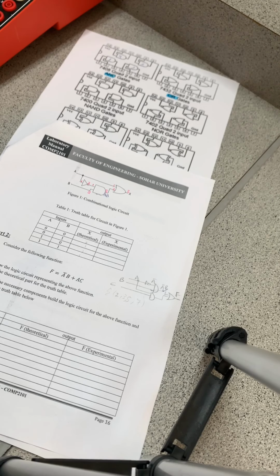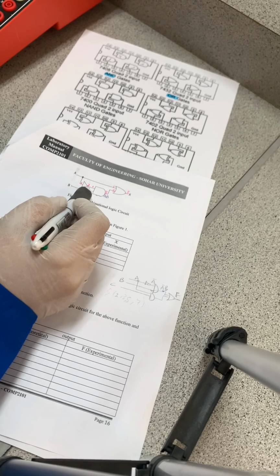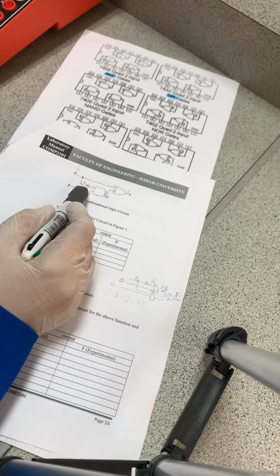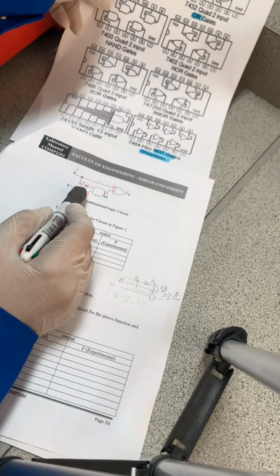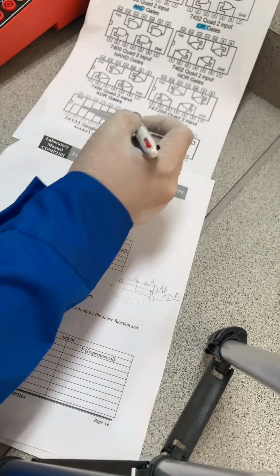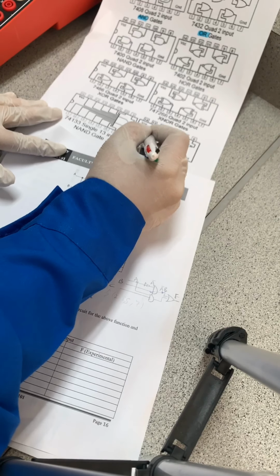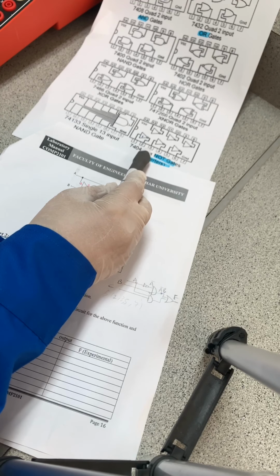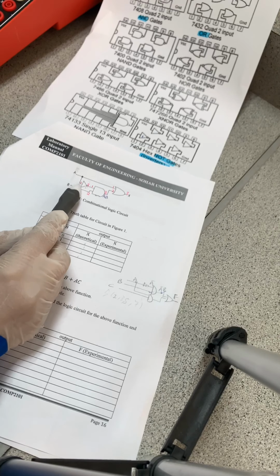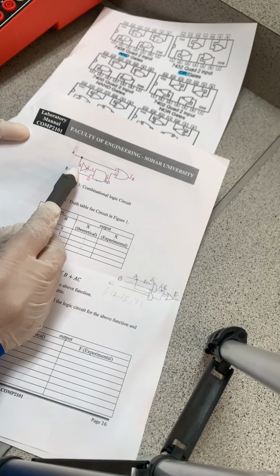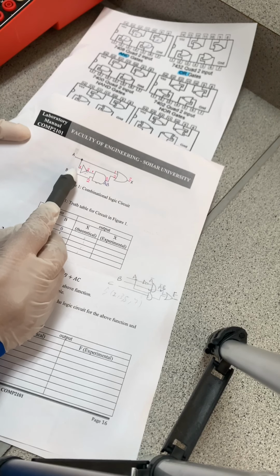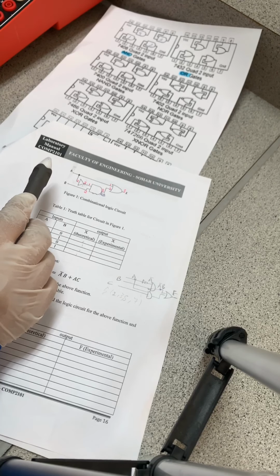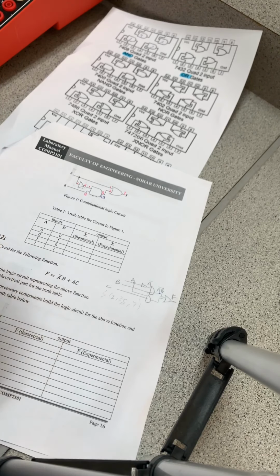So, for example, the first gate we met was the inverter. I go back to the specification of the inverter. For example, I will take the first inverter, dealing with pin number 1 as an input and pin number 2 as an output. So I assign it here: this is pin number 1 and this is pin number 2. So now I know that the inverter I am going to deal with uses pin number 1 and pin number 2. Okay, let's go to the AND gate, which is 08.